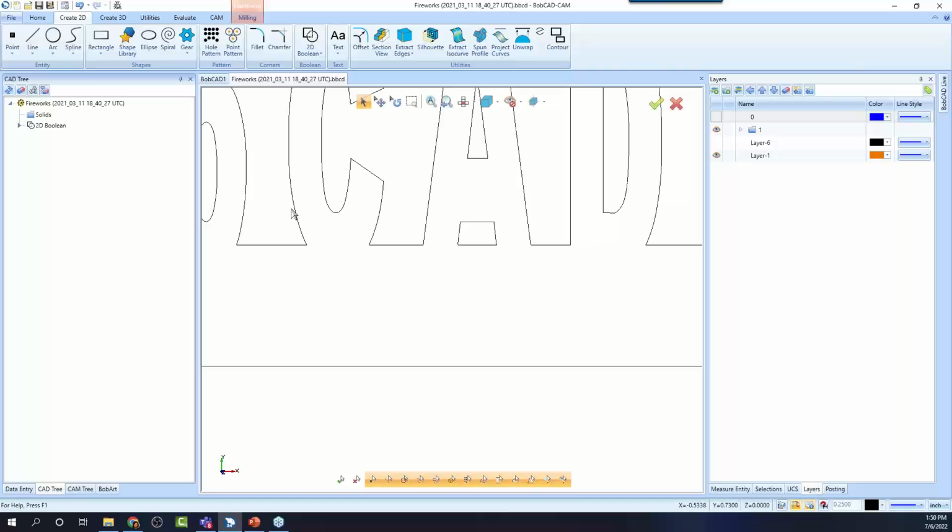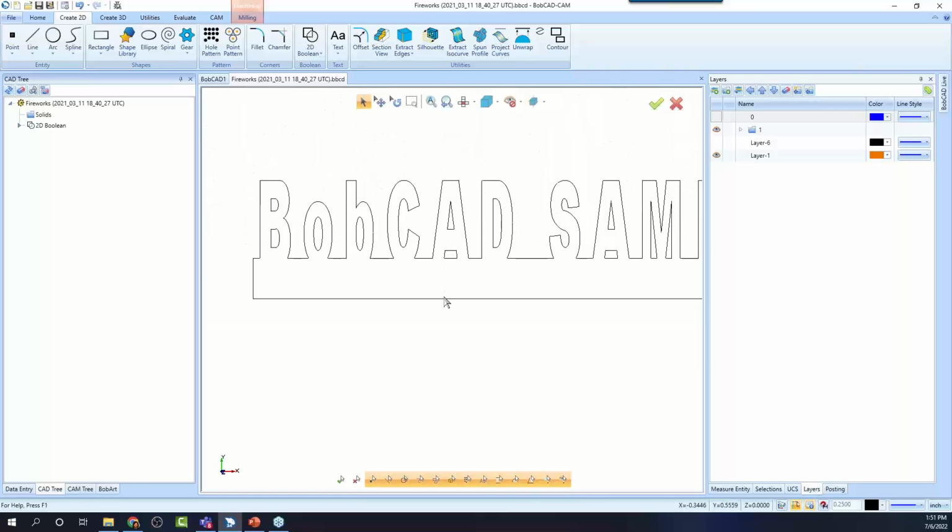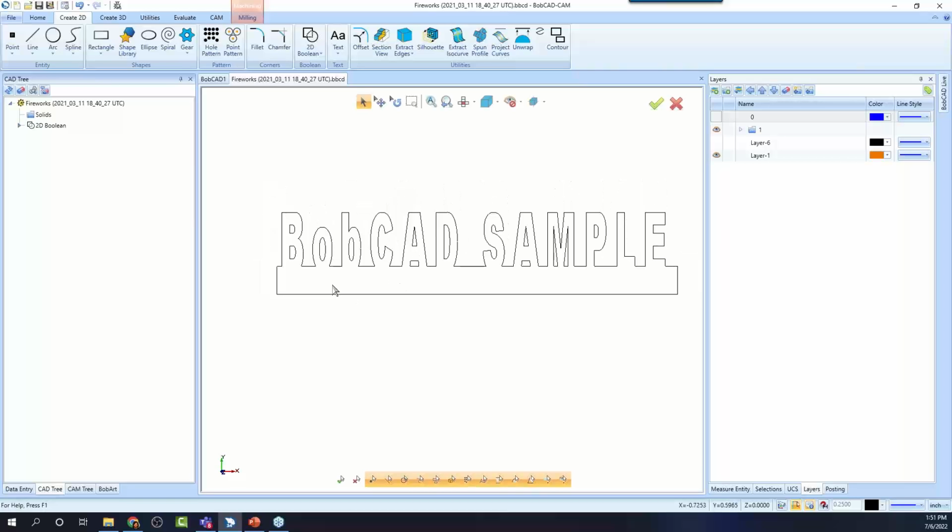There are some tolerances with arcs. If you're working with a lot of this geometry, you definitely need to talk with the post team about all the arc handling features we've added over the last couple of versions, as far as how we break arcs, how small, and posts and line segments can really make a difference to your workflow for shape cutting applications.